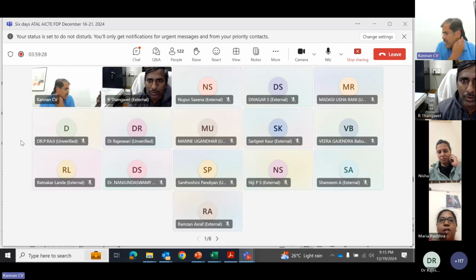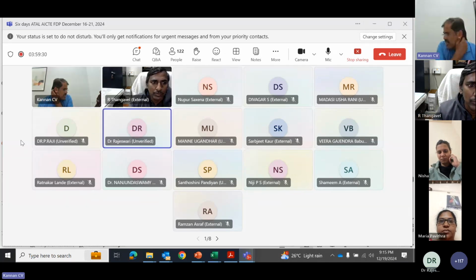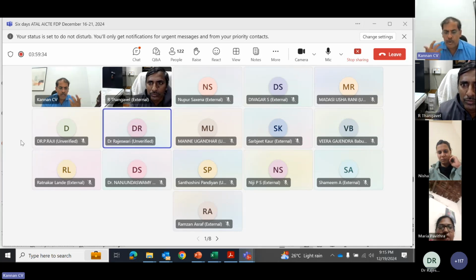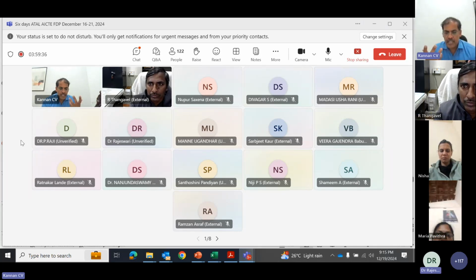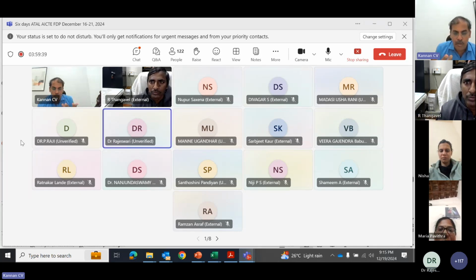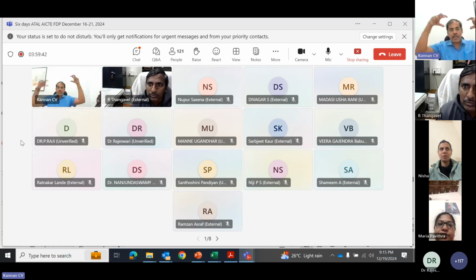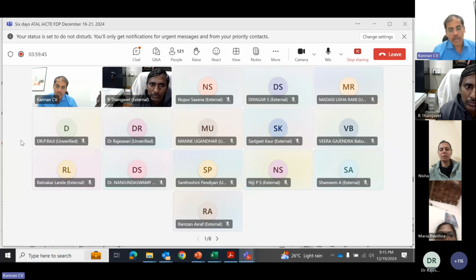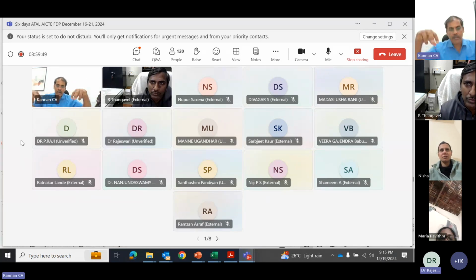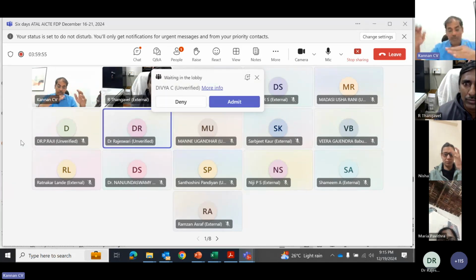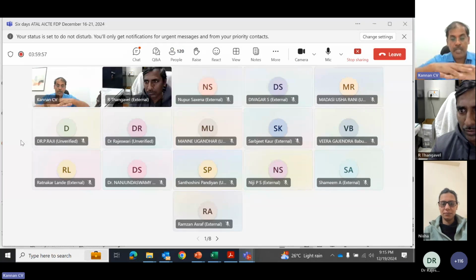No, you cannot get the pure silicon, because you have already made the boron diffusion. The substrate itself comes with either boron dope or phosphorus dope. Only the raw material is pure polysilicon. After that, you are intentionally doping boron and phosphorus, converting into dopant. Then you convert again: if it's a p-type wafer, n-type diffusion, so that you get the p-n junction.